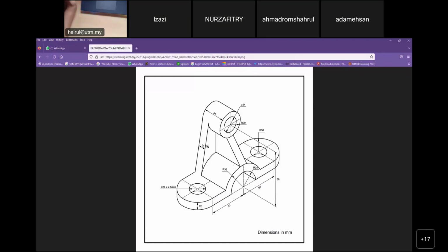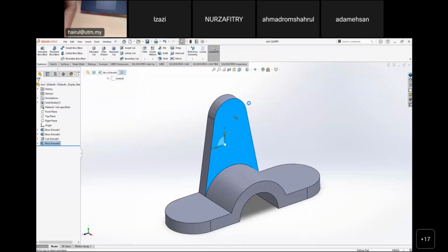The balance I have 12 here, so 22. I have to extrude another 22 of this protruding cylinder because I already extended 12 here. So in total from the back it's 34 minus 12, which means 22, right? 22. So at this plane, I make a sketch.